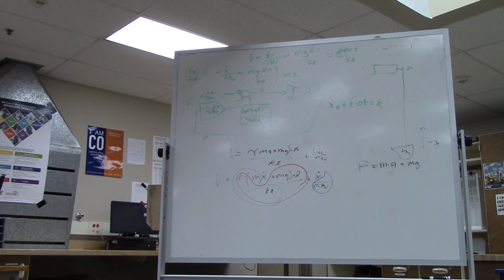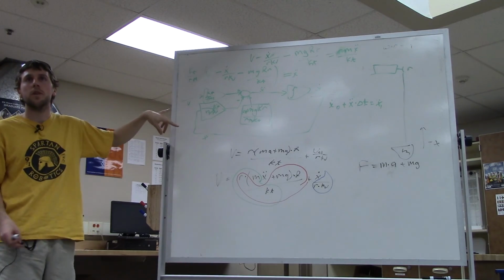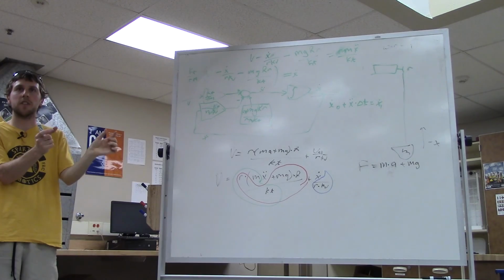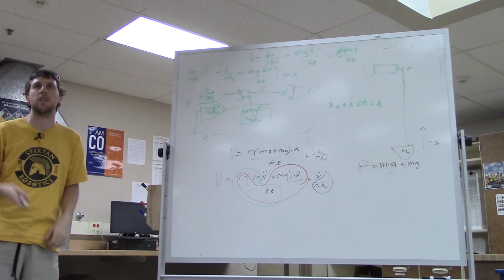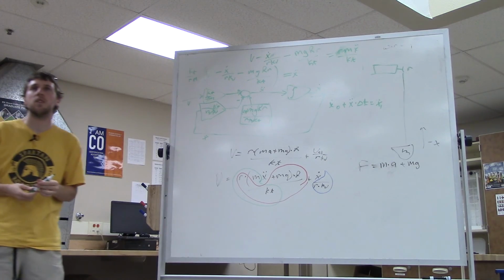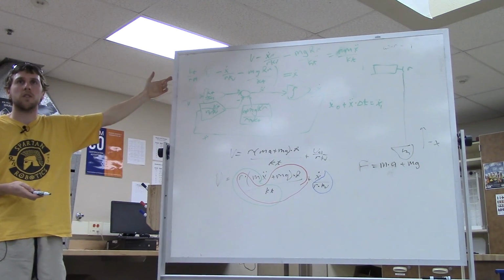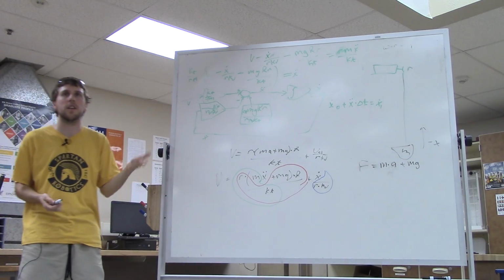Sometimes when you have a system you have to control, your velocity and your acceleration, right? And in some cases, you want a much faster acceleration and deceleration versus a slower one. How do you adjust your model to fit? Your model doesn't change. What you need to change is what you're doing. So this is where you change your controller. Where we had, and I erased it, a PID loop, we had a reference position and velocity, you can feed it a nice smooth path to follow. That's called motion profiling. But in the end, it's the same physics that applies. We're just going to be less aggressive in the voltage we request to get a less aggressive response.